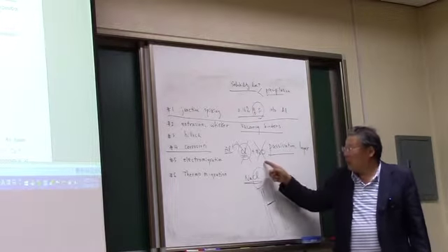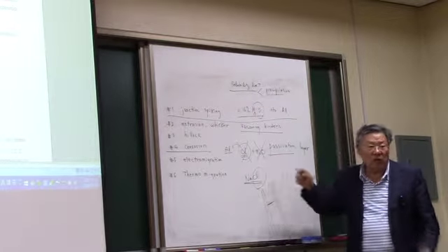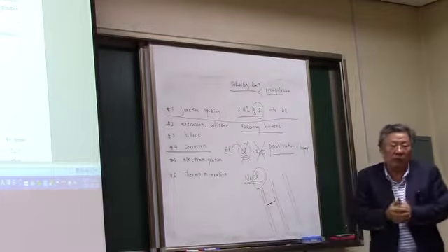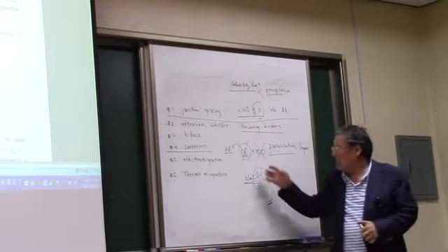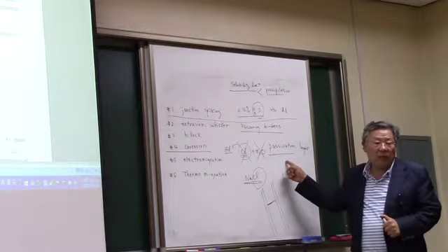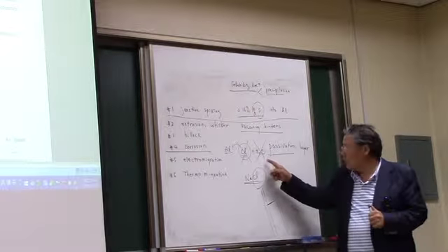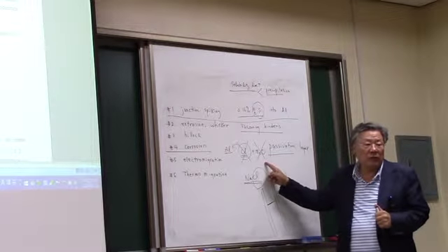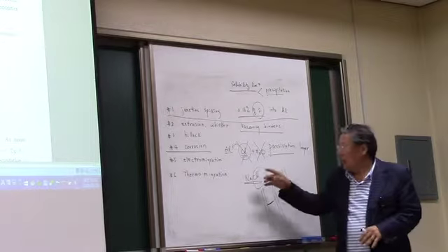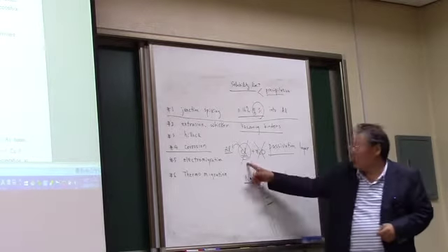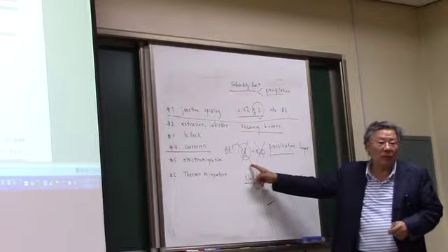But if you get rid of this moisture completely, then chlorine itself is not going to react with the aluminum. So with a good passivation, you're not going to have moisture in your device, and with good cleaning, you're not going to have any contamination with chlorine.